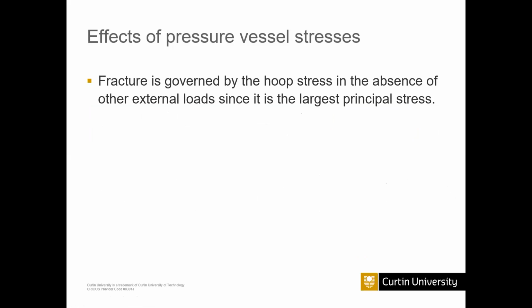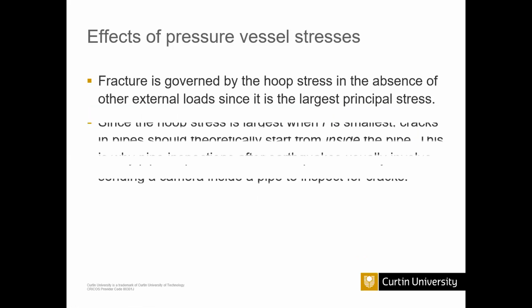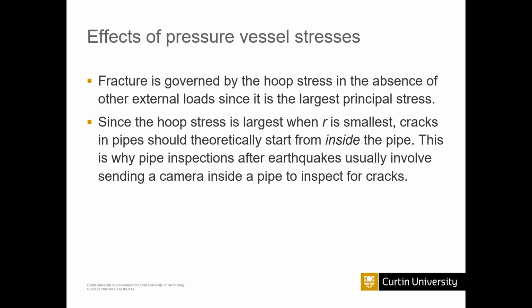Normally the maximum stress is given by the tangential stress, and so normally we will use a thick wall cylinder for the pipe. You know, the oil will be transferred by the pipe. We call it a thick wall cylinder.